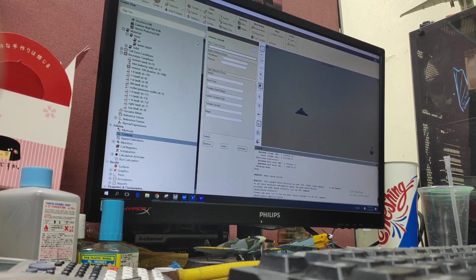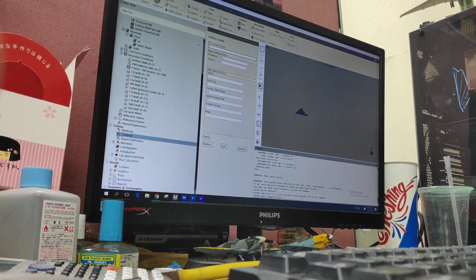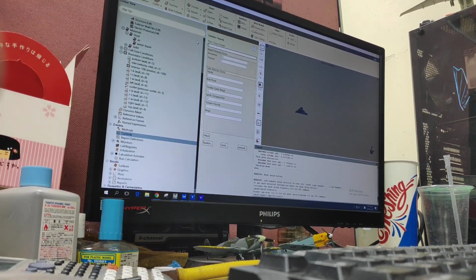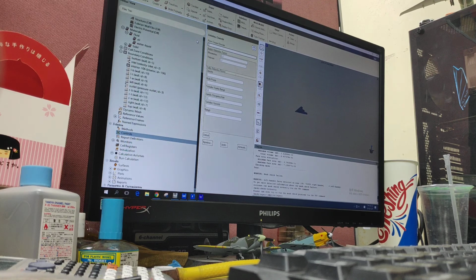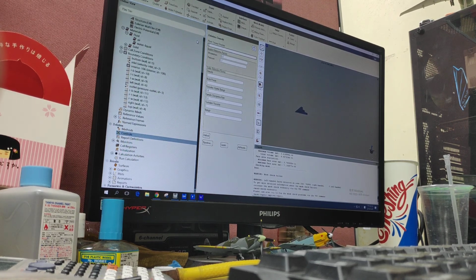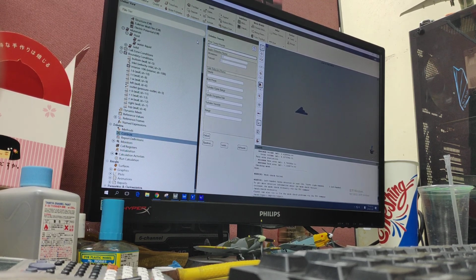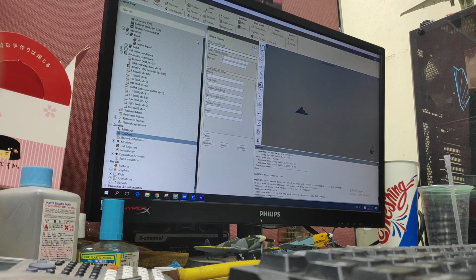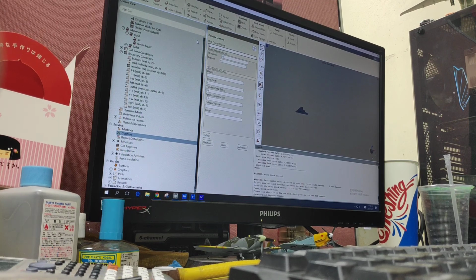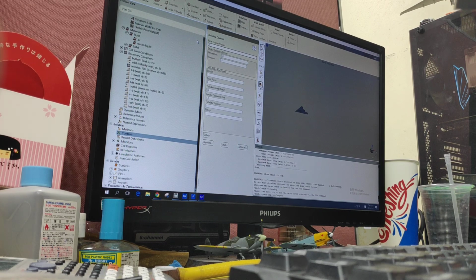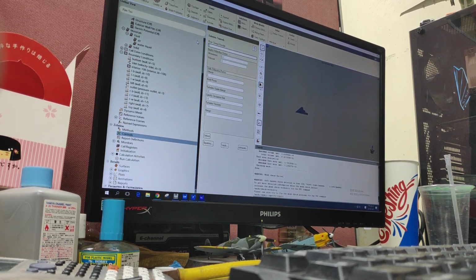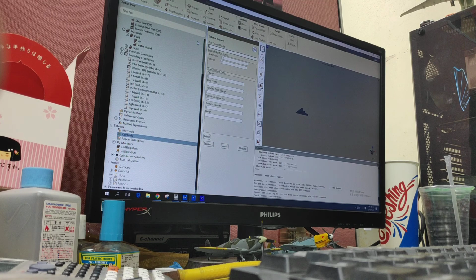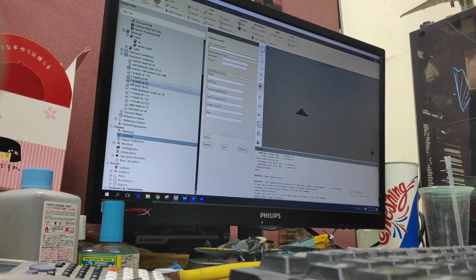It's case by case, but mostly we just set to 5. If one day you set it to 5 and it's still a problem, maybe very hard to converge, or it diverges, then you can change the courant number.